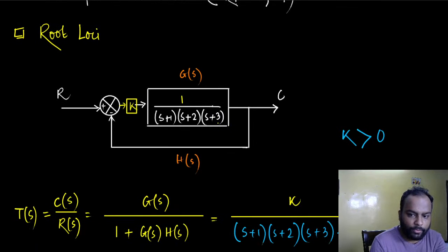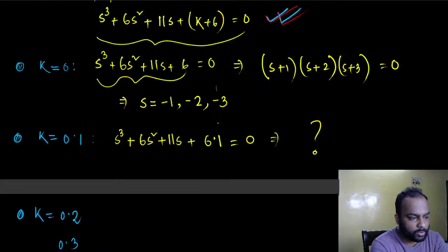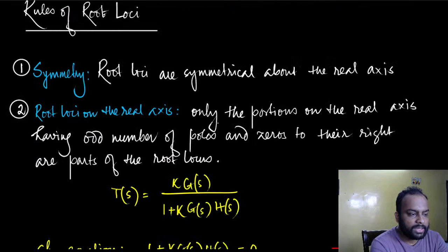if you recall, we figured out three very important things about the root locus. First of all, root loci are symmetrical about the real axis. That has to be true because the polynomials we are essentially trying to solve, or maybe not solve, have real coefficients. It is one of the fundamental theorems in algebra that if a polynomial has real coefficients, its roots can only be real or complex conjugate pairs.